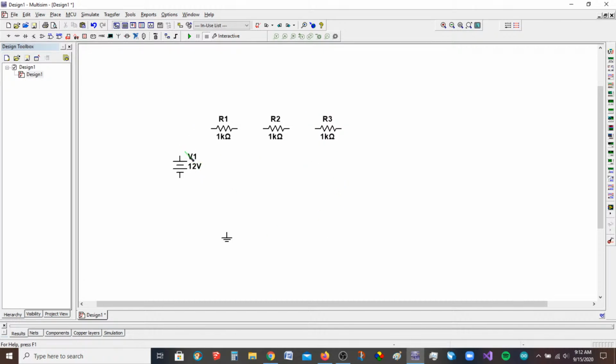So if you want to connect a wire from a piece to a piece, you can see that as I hover my mouse over any point, any junction, I get that little crosshairs. Okay, and so this is not a click drag. This is a click, move the mouse. You get one 90-degree turn wherever you go. That's it. If you need to make more, then wherever you want to pivot, make another click, and then you get one more 90-degree turn. Okay? So it's kind of like an Etch-a-Sketch to some degree.